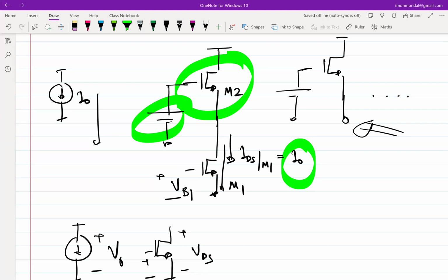Yeah, true. What she is pointing out is, let's say I have 10 of them. So I connect one here, one here, one here, and then put a current source there. But these types of circuits we are going to use for some purposes, right? So ultimately, biasing is just a means, but there is an overall purpose that we want to serve. Just because I'm not able to bias, I don't want to change that configuration. Yes, we are using that property of the transistor which makes it behave like a current source. But the issue is the current is not constant with the change in temperature or threshold voltage.